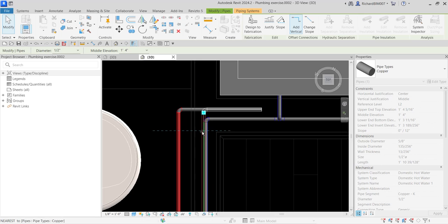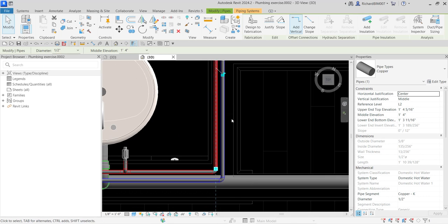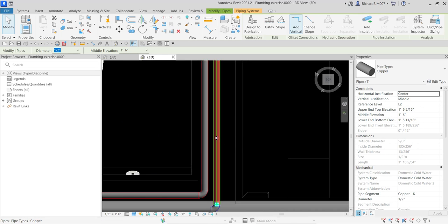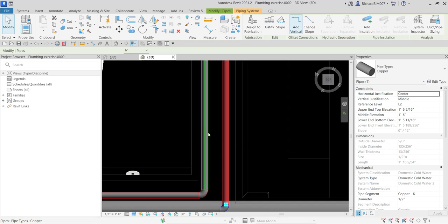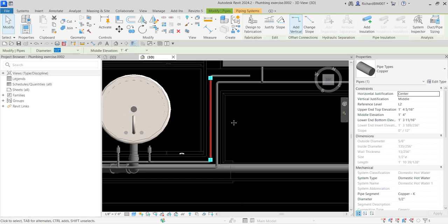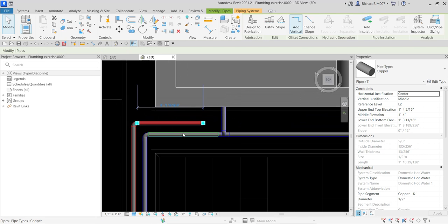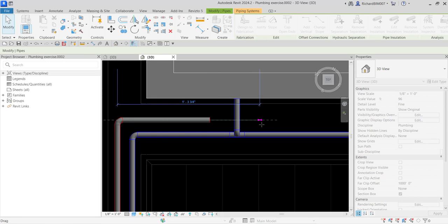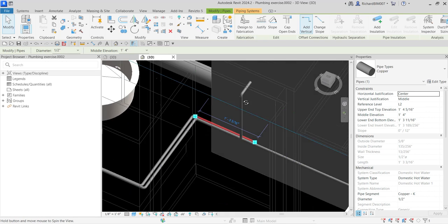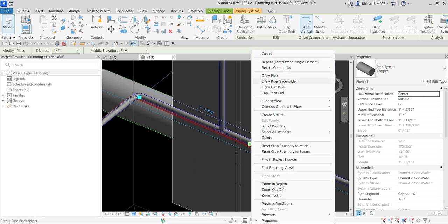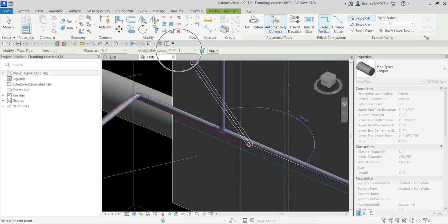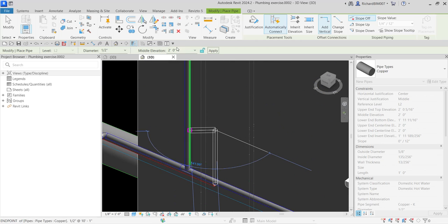Drag this inside without touching. So maybe I click this one and then use the arrow on my keyboard just to move it. Alright, so let's click this one. There you go, and then orbit, click, right click, lower value like 2 feet. Okay, if you select apply, it will terminate the connection of pipe like this one. Apply, so it will terminate, right?